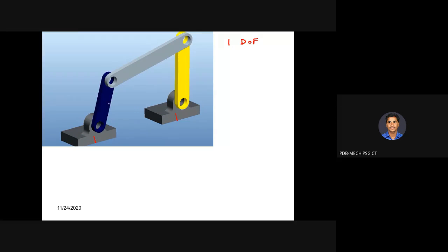So what is the next link? Coupler. The coupler, sir, left side. Yes, crank or input link. So that is the second link. This coupler is the third link and the output link is your rocker. Just try to remember the names. Definitely rocker, then here crank, and this is called coupler. Then this is frame. This and this are frame.